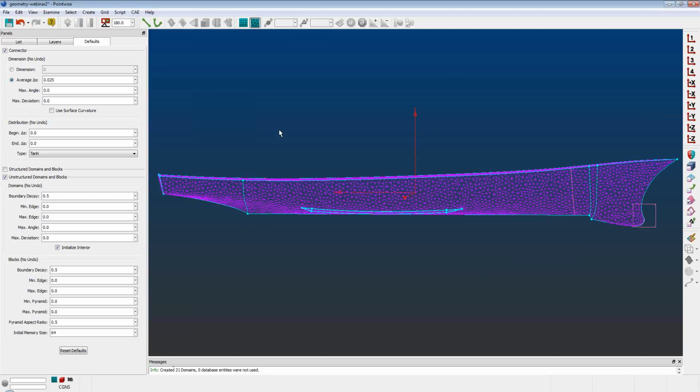Firstly, when you added the keel onto the bottom of the ship, is it possible to add such a shape across multiple surfaces rather than the single surface you added it to? Yes, the trimming operation would work across multiple surfaces, because we're actually trimming the models together. We have a model for the bilge keel and a model for the hull, and those surfaces comprise each of those models, so we're really doing the trimming at the model level, so it can handle trimming across multiple surfaces. Yes. Okay, great.